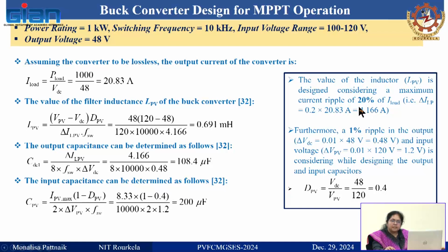You can make it tighter, 10%, or 1.05, or I may explain with a 2% voltage ripple. The design guideline is between 1 to 2%, or a maximum of 3%, for the voltage ripple, and the current ripple between 10 to 30%.